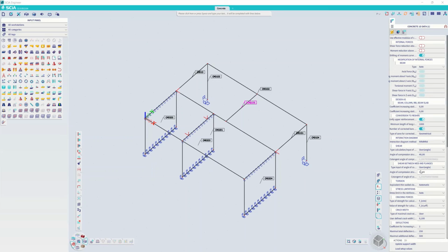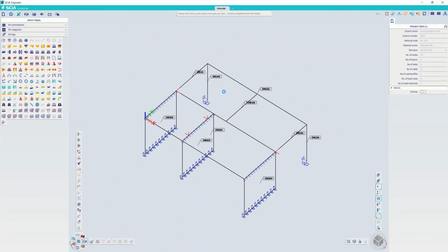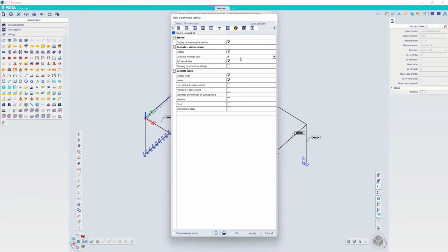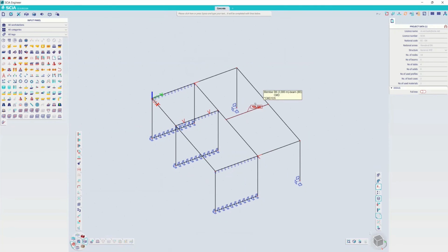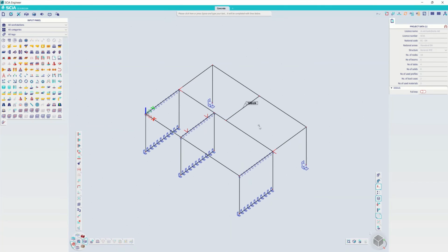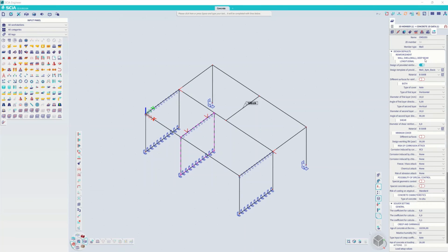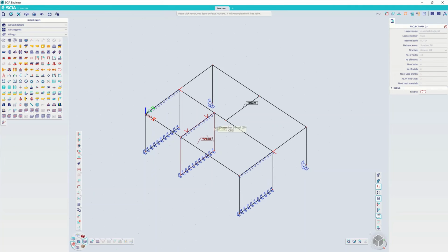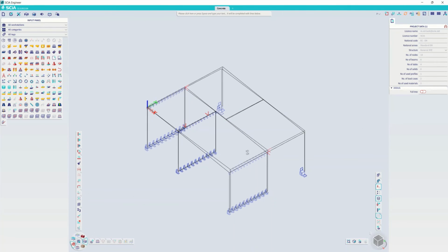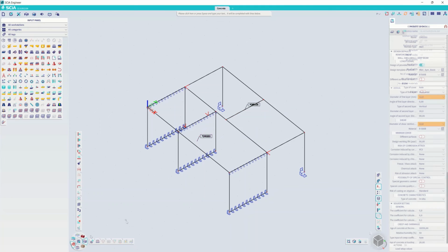What I'm going to do now is change the angle of compression strut for shear design, for example, and then switch it back to different from global setup or concrete settings. And then you will see that only this label is visible. And the reason is because we changed some values in this concrete member data. Let's do the same thing for this 2D element, change the diameter of reinforcement. And you will also see that it gets a different color in the properties window. And now also this label is visualized in your project.